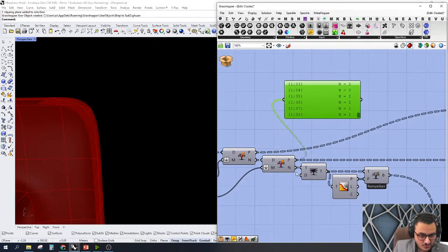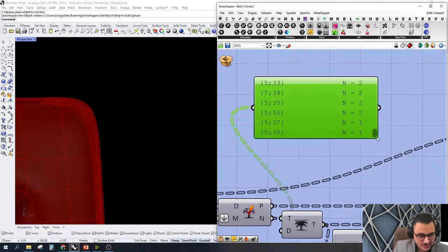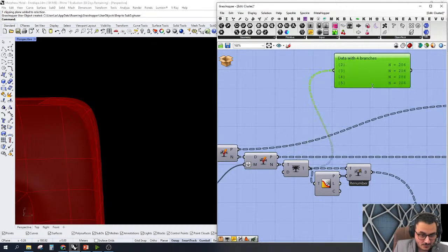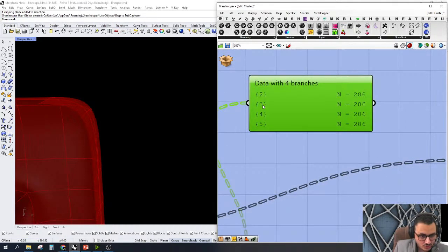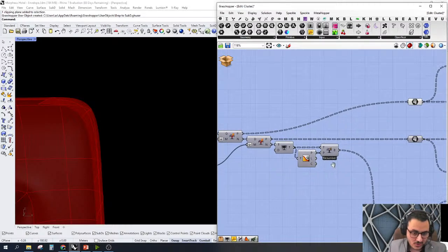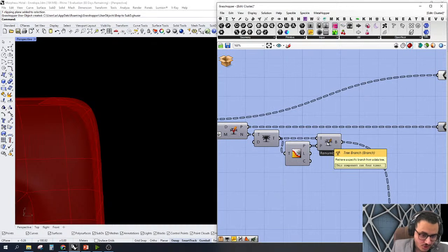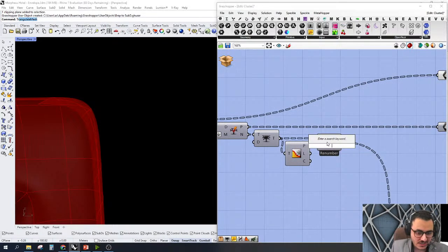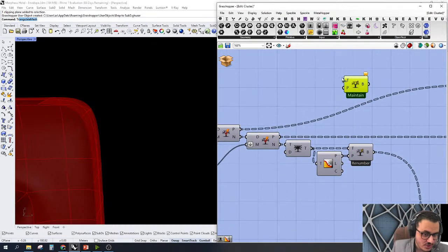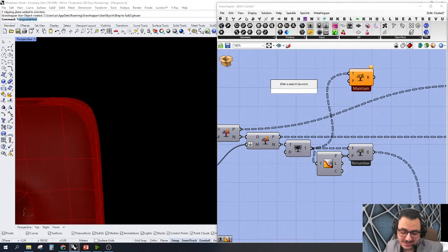And in this case, if you saw in here, you can see that 5, 4, 3, 2, these are the negatives. I split them back to become 0, 1, 2, 3, and this is a great component called tree branch. Let me show you what's happening. TRBR, tree branch. Tree branch is great because if you want to select a specific tree, let's say 0.